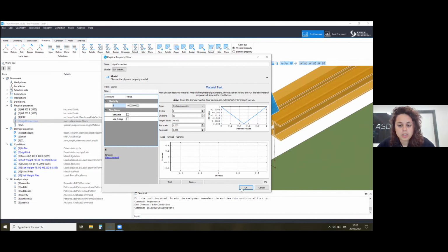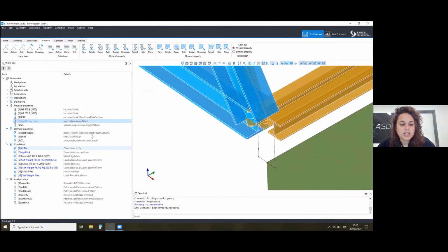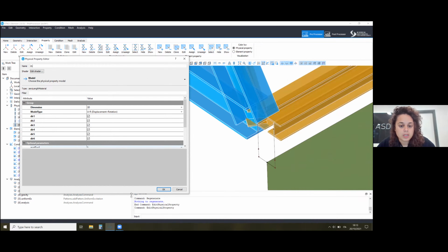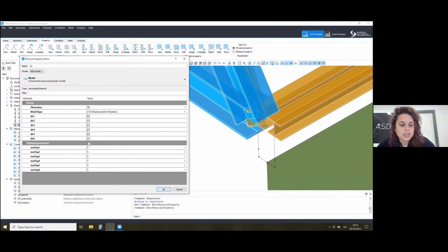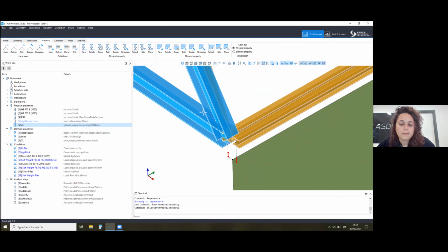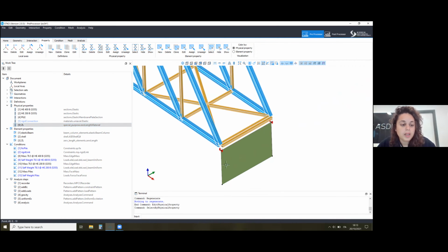I want it to be rigid. And then you assign it to a zero length material in all of the directions, which you directly assign to the interaction just by drag and dropping it, as you do for assigning physical properties to faces or to edges. So it's the same way.